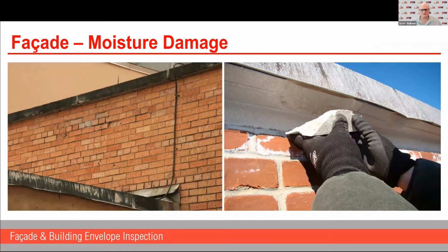This is a picture of some moisture damage to brick veneer, and moisture, of course, typically gets in through the capstone here. You've got sealant between the pieces of capstone. That's an organic material. It's going to break down, subject to UV exposure, not to mention just old age, and allow water to saturate this wall. And when you get water in that wall, it deteriorates the face brick in a number of ways.